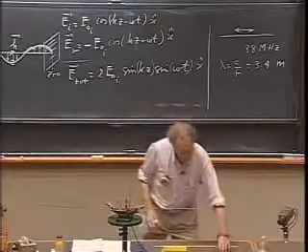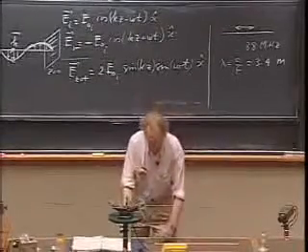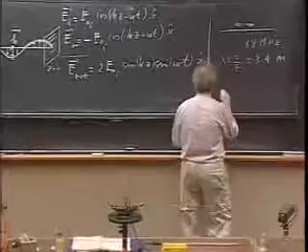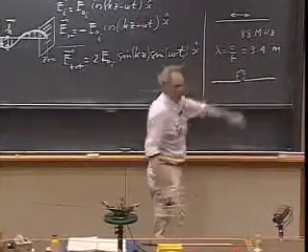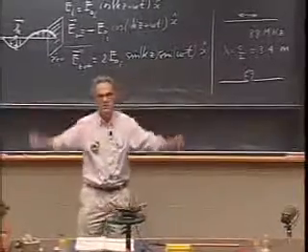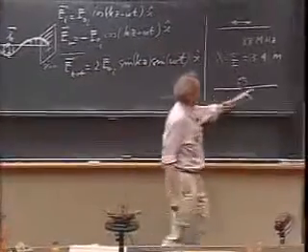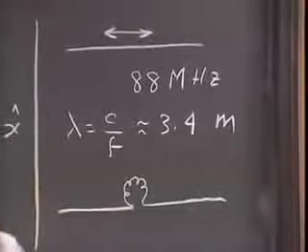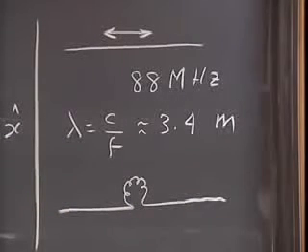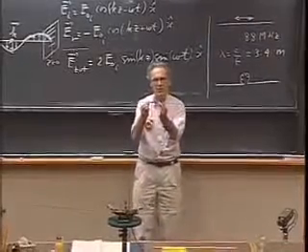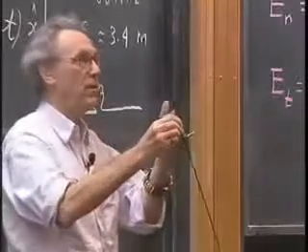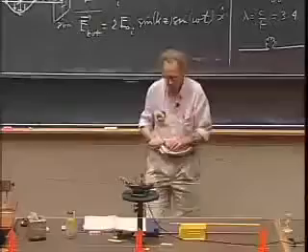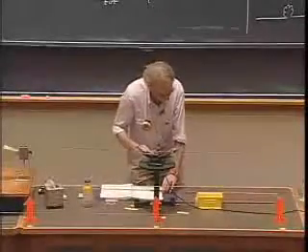And I have here a receiving antenna, which is just two copper wires which are not connected with each other. Well, they are, but they're only connected through the filament of a light bulb. And so when the electric field reaches this receiving antenna, currents will start to flow in this direction, and then the light will go on. I've demonstrated this before, but I want to do that again. If I hold up this receiving antenna like this, then you will see the light bulb go on. If I do it like this, then it will not go on, because no currents can flow then in this direction. But that's something I already showed you before.